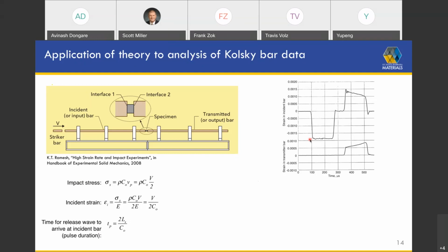I think so. Let me perhaps paraphrase it to make sure I understand the point. As a practical matter, the way you assess strain rate sensitivity depends on the domain that you're in. Let's say we're in this dynamic domain, not in the creep domain. If we're in this domain that we're illustrating here with a Kolsky bar, the way you probe rate sensitivity is simply to perform experiments at different strain rates.